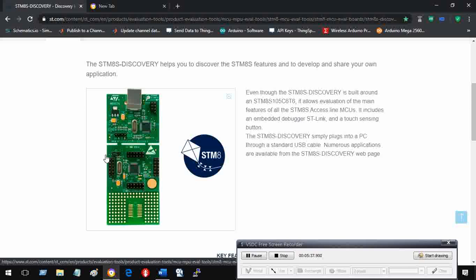This is currently connected to this evaluation board. You can do a lot of experiments around a microcontroller, the STM8S105C6. You can do that. But this part, whether you cut it from here or you let it remain here, you can connect this to a target board, and these are the 4 pins which are connected to the target board pins via a 4-core cable, right?